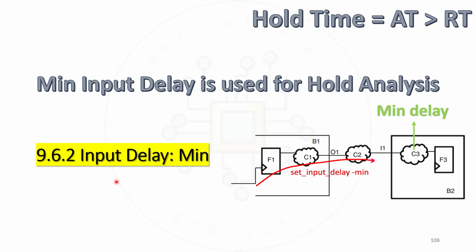In the previous lecture, we have seen about input delay max. Now let us see about input delay min in this particular video. So we already know that min input delay is used for hold analysis, and for hold this condition should get satisfied, that is, arrival time should be greater than required time.